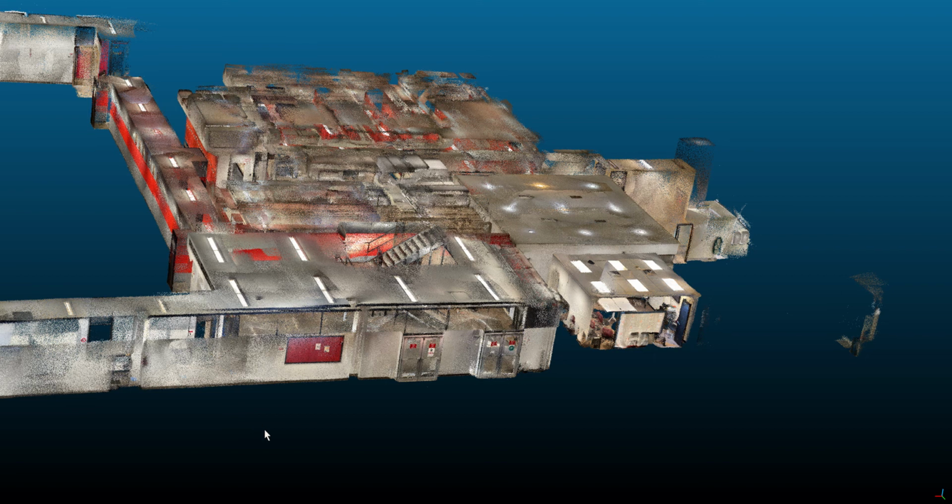The next challenge was that sometimes the scans wouldn't all open on the same plane. This was particularly an issue with the scans in the men's locker room. They were all in different locations on the X, Y, and Z axis, so it was kind of a big cluster. What I did first was put everything onto the same position on the Z axis so that it would be easier to work with.